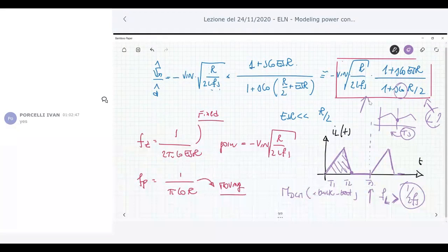So no inductance pole is included here. Okay, in CCM you always have two poles because you have two reactive elements, inductance and the capacitor. Here in DCM, and this happens for all DCM circuits, not just the buck boost, the same is for the boost, and the same is also for the buck. In DCM, there is this missing pole due to the inductance, just the one due to the output capacitor.